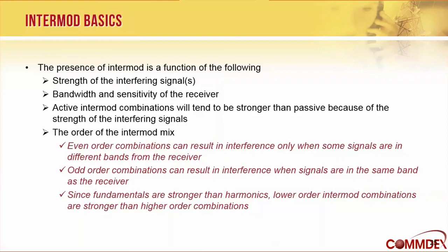The order of the intermod mix: you can get even order combinations or odd order combinations, but the odd order combinations are generally the only ones you care about, because when you do the math, they will be the ones that result in interference in the same band as your receiver.